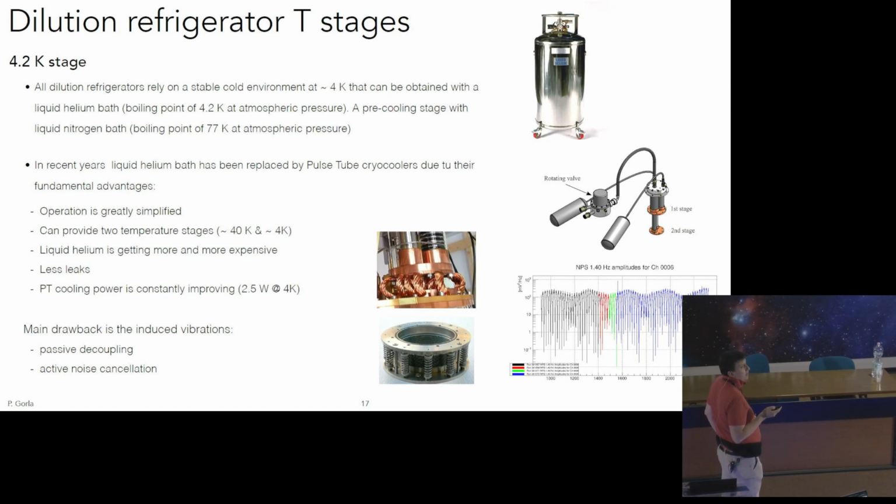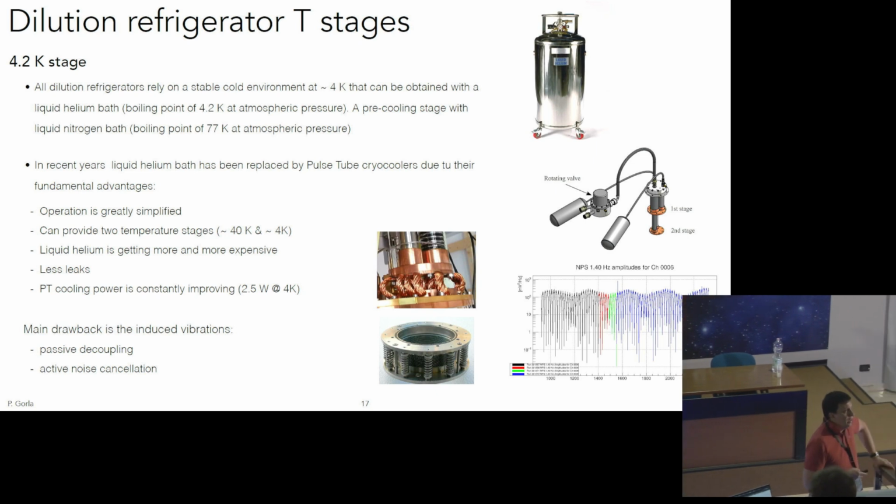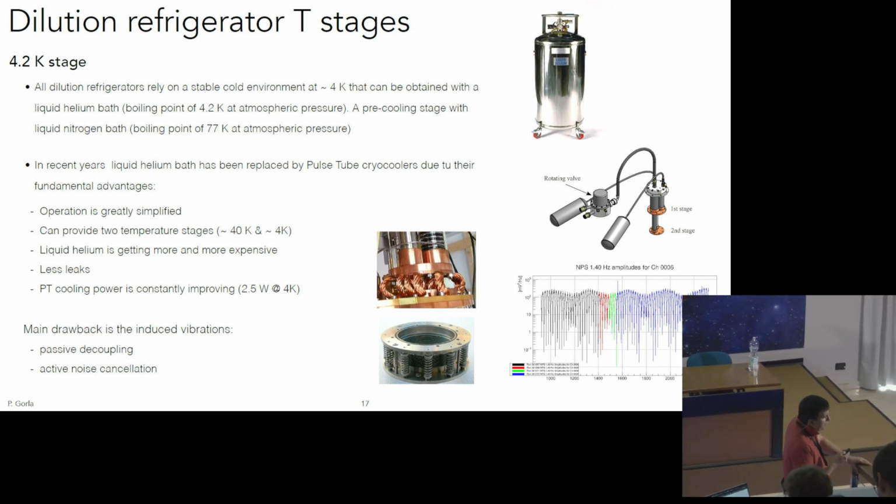One other thermal cycle that is very popular for cryocooler is what is called Gifford-McMahon cycle, in which the compression expansion is done with a piston that goes to low temperature. So you have always a moving part that has to be at low temperature, and which also induces a lot more vibration because you have really a bumping piston all the time.